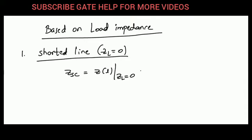So this is from the impedance transformation relation, and we will get j Z naught tan. Okay, before this, let me modify the impedance transformation relation for a lossless line so that we can get it easily.